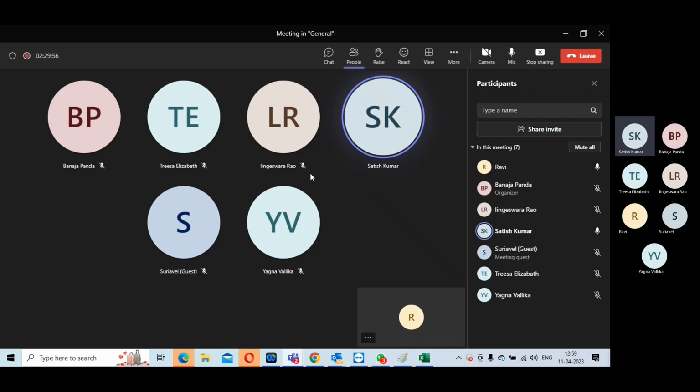In my block, it was from top to bottom. If there is any crisscross, I used to inform the top level about the placement. They will align, and then they will align the feed throughs. Wherever you have feed throughs, add partial blockage on that path, because if you overutilize, it is going to consume routes also, and then you won't be able to do it. That's where you have to look at overall utilization.